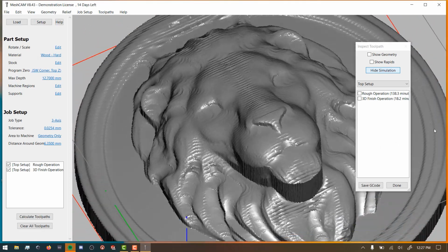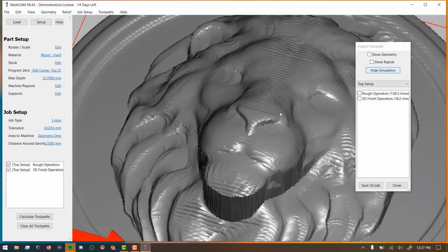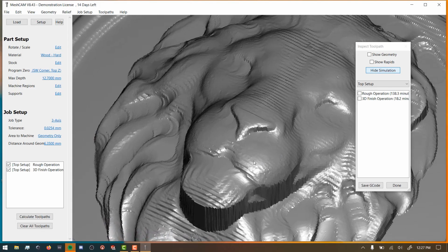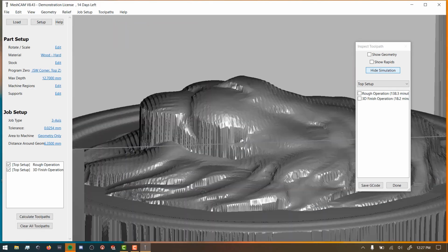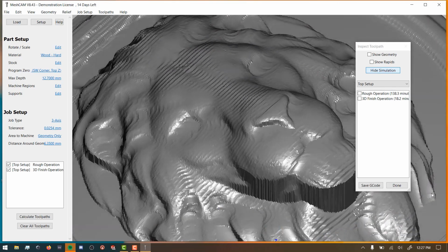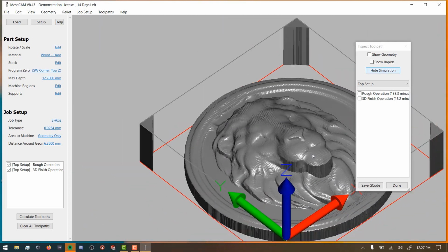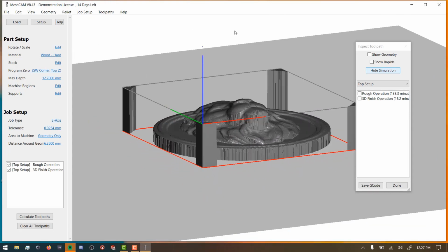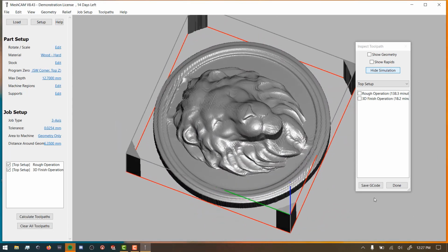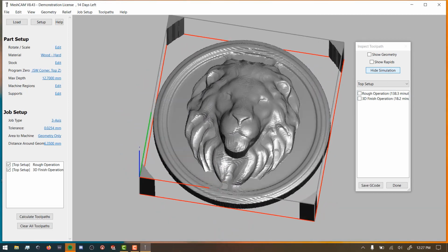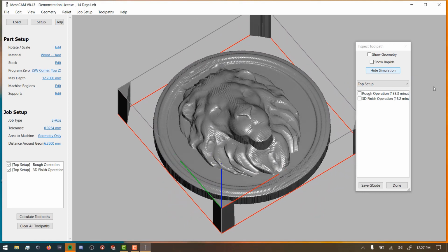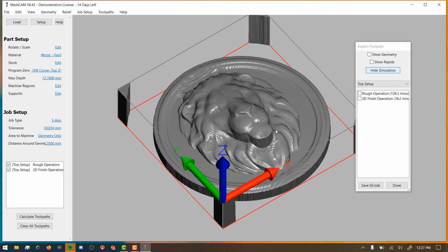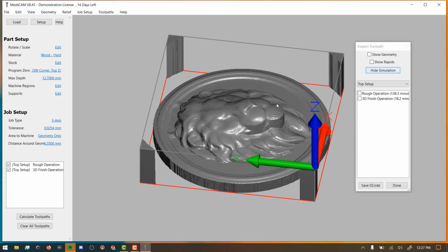That's because we're using a pretty standard 2mm flute flat end mill, and the flat end mill is where we're getting a lot of the stepping here. Now, for your first project, I think this is absolutely serviceable, and this looks fantastic as a piece, and it's something that I think is a good first run. If your machine can make this, then we can step it up later with some fancier end mills, like a ball end mill or something like that, that can really take this to a nice finished look.